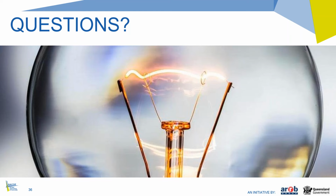The difference really is you're talking about milliseconds, I guess, to do the iterations in CIRCLY using the automatic thickness method or the automatic thickness option in CIRCLY. You're probably going from milliseconds up to maybe 4 or 5 minutes to do those iterations manually. So I don't think that's a major onus on designers to do that. Well, I think to save millions of dollars, a few extra minutes of your time is a small price to pay, I would say.